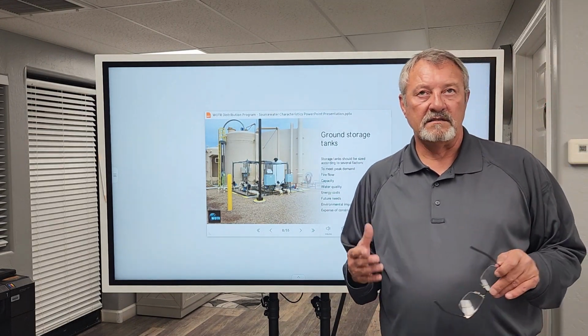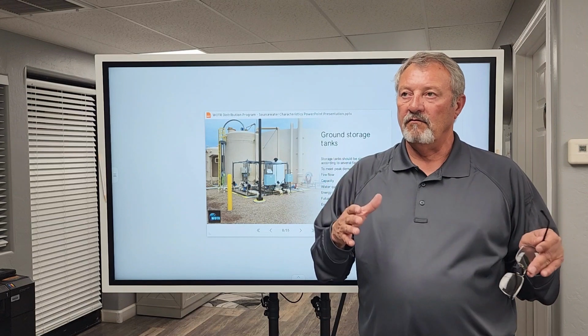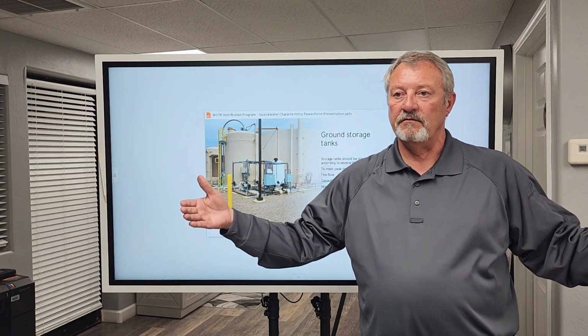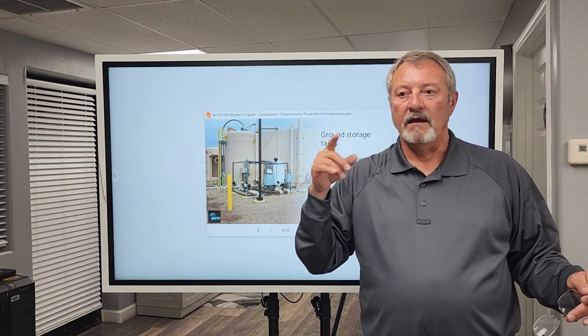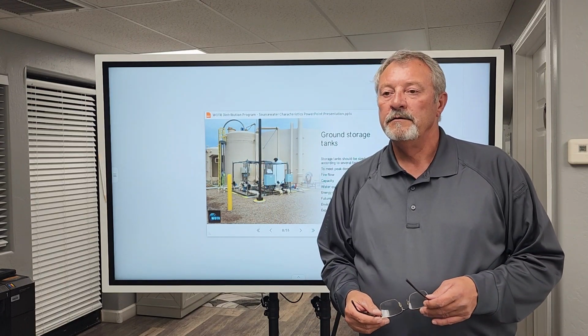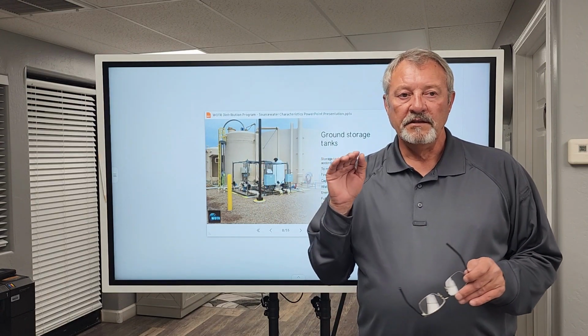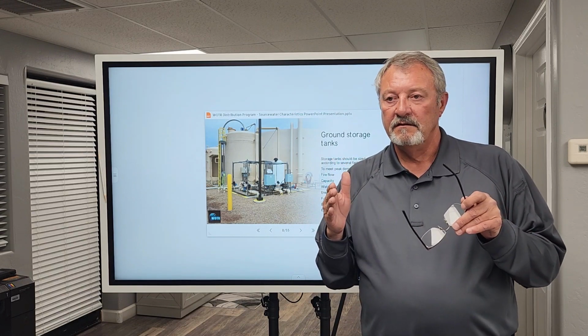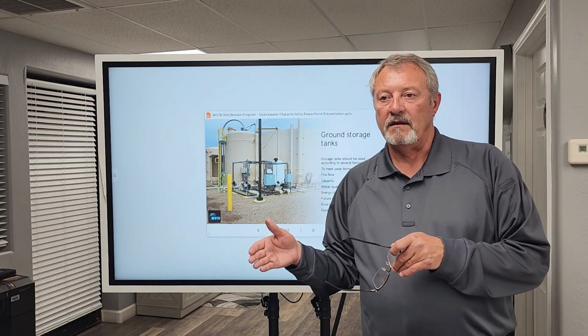Okay, so what do we mean by peak demand? Well, what we can say is if you take the amount of water you deliver to the customer over a 24-hour period, divide that by the minutes in a day, 1,440. Yep, 1,440. Then you'll get your average demand in gallons per minute.